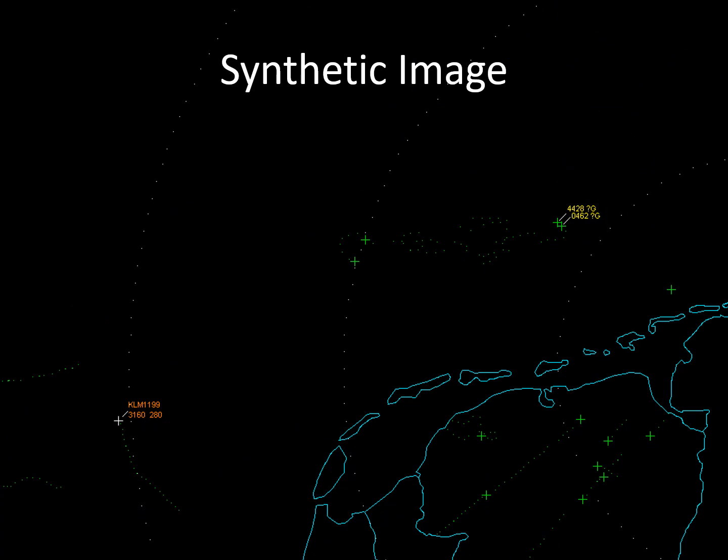To generate such a synthetic radar image, not only the fixed targets have to be suppressed. With a plot extractor, symbolic target signs are generated from the analog or already digitized radar data, which still describe an echo signal. Up to then, it was called radar signal processing.